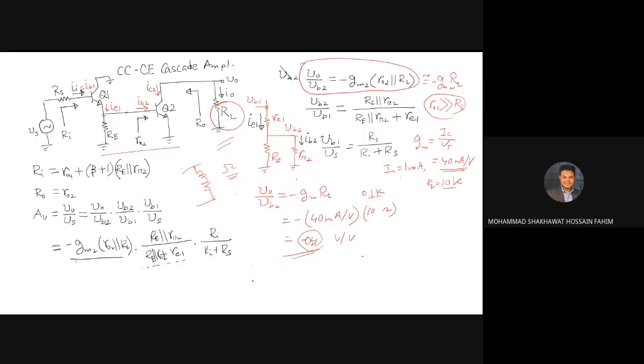Sir, add a series resistance with RL. Series resistance, yes. So how will that help? You add a series resistance with your coil, with your speaker. It's the RS, and that is the V naught, and the coil, that's the coil resistance, will get only a small fraction of this voltage.